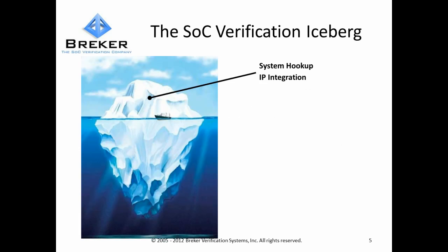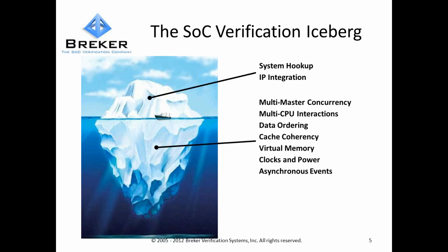Today for system-on-chip verification, we're generally seeing that work is done mostly by handwritten directed tests, typically written in C, that are compiled and run on the CPU. I don't know why, but every SoC integration team seems to have exactly 2,000 C test cases. It's never 2,500. It's never 1,500. And the combined suite of test cases typically focuses entirely on the basic IP integration testing, the so-called tip of the iceberg. We know as verification engineers that we've got to do much more than that.